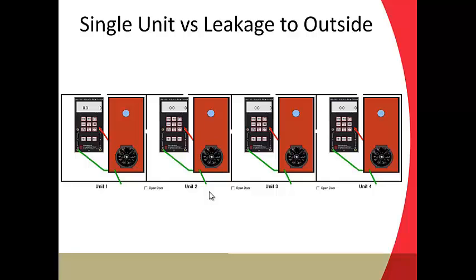Next, I'm going to use a simulator to do tests on a 4-unit townhouse type building, and these leakages to the outside and to adjoining spaces are based on an actual building. So the default that I'll be using with this simulator are based on an actual test.